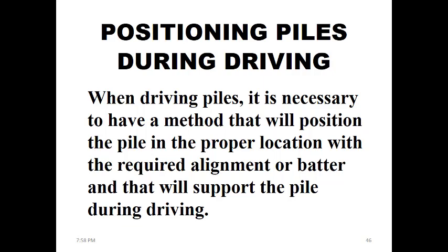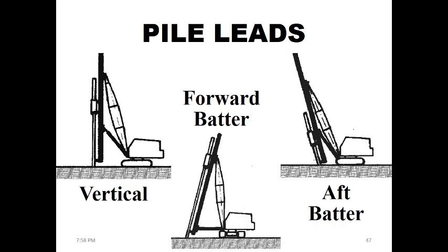And depending on the operation of a pile, the positioning will be different. We may also decide to drive it under certain angle if necessary, just because we need to support the loading forces. In this case, we see these three different positionings, and the first one is the vertical option, while for the other two cases we see that the machine can position it under angle depending on how you will put the machine in the construction site, the crane, and how you should position the pile itself for driving it.